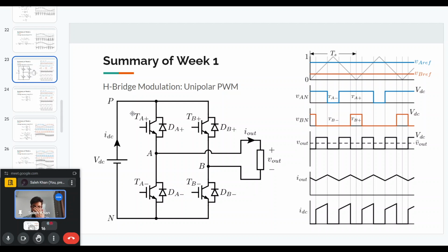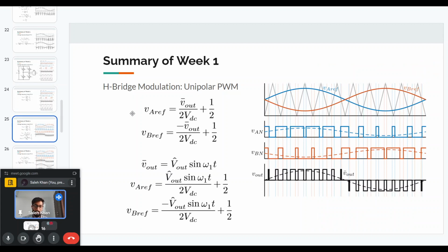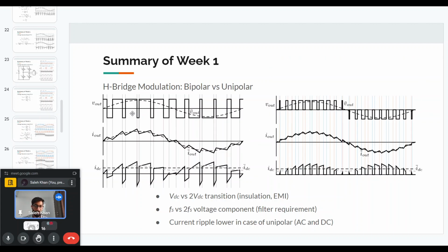they will provide this current while the DC battery or the DC source will only provide the DC portion of the current. But in practice, the capacitor will not be able to filter out the current completely. So the battery current will not be pure DC. It will have some AC components. But basically, the capacitor is used to provide the ripple portion of the current.